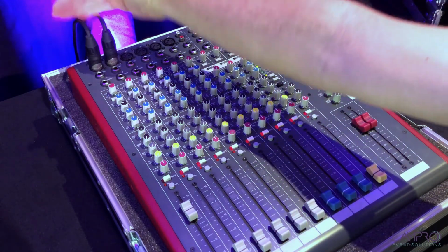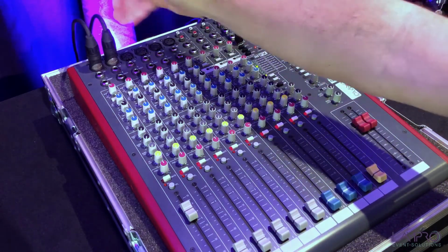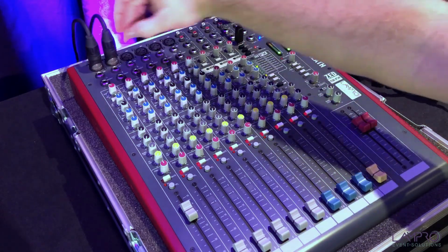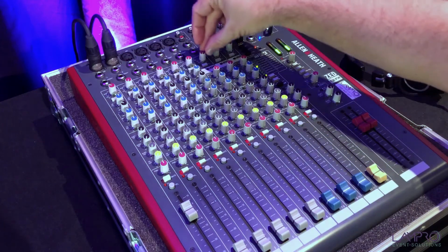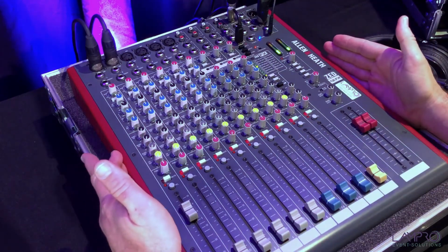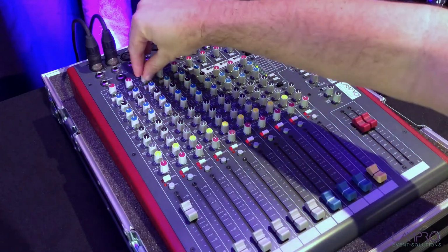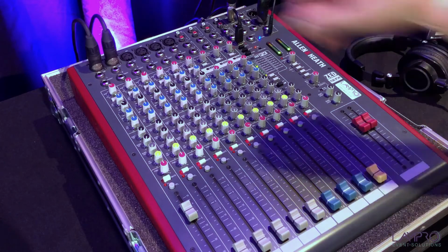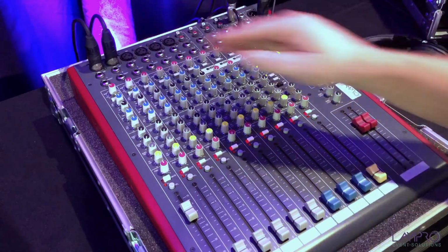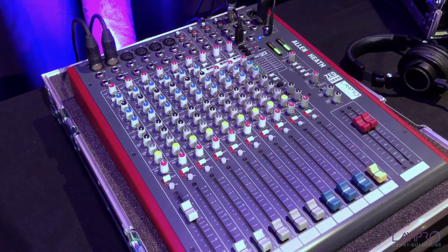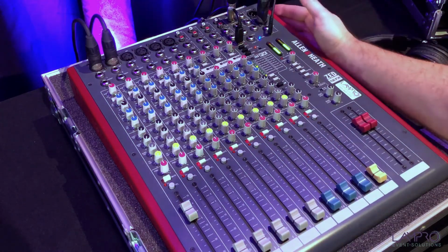Regardless of how many mics or instruments may be connected to any of the inputs here, whether it's the mic inputs or the line inputs, you need to make sure that your gains are set correctly in order to get the correct audio levels coming into the console. If the gain has been set up too high, you might end up with distortion, and if the gain has been set too low, you might not have sufficient audio being passed through into the channel that needs to be sent out to your outputs.